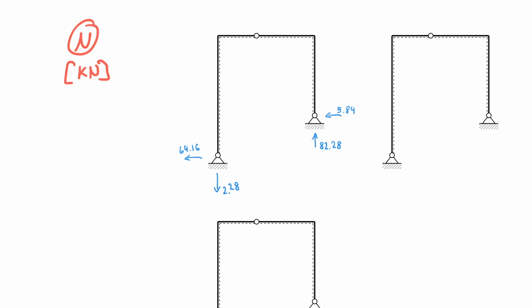So in member 1 on the vertical left part, the only thing that acts in line of the member was the vertical force. And see that here we have 2.2 pulling downwards. That means that this entire member must be in tension. I don't even have to make a cut to do that. I mean, a beginner should always make a cut, but I can already see that there must be a normal force that is in tension, and tension is positive, and also it's constant. There's nothing else that pulls on that member.